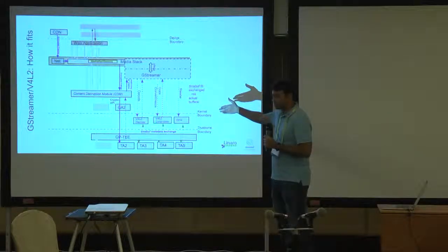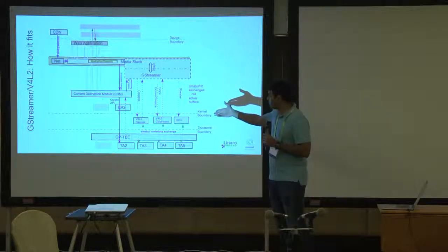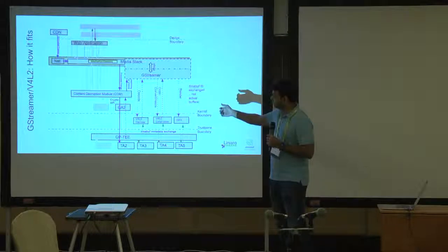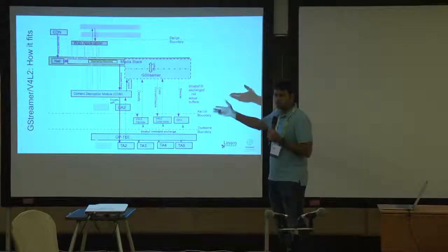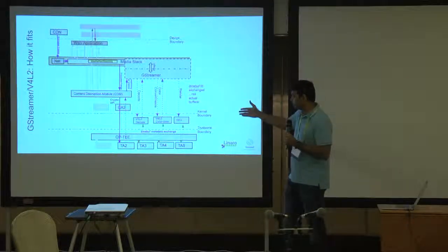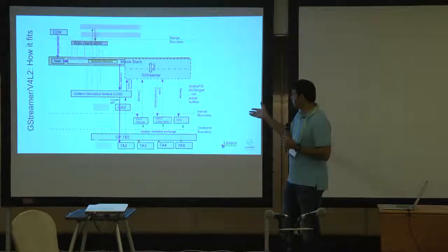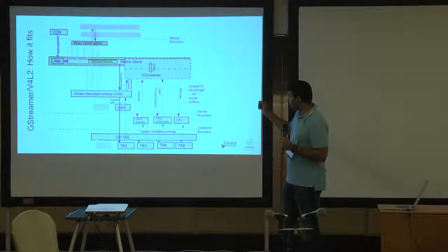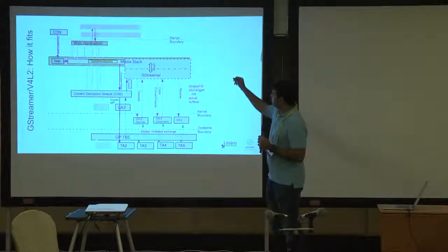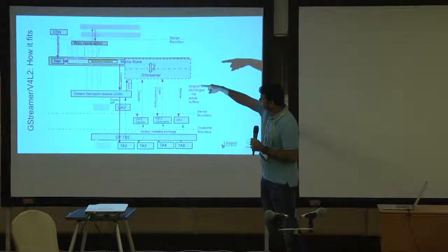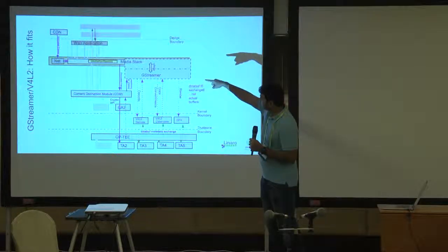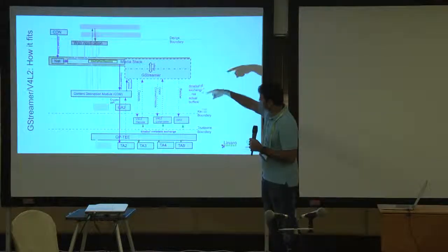You have V4L2 based color converters in the kernel. An example is the VPE engine from TI, or any other color conversion or scaler that can scale the images. And then you have a graphics engine. So GStreamer pretty much becomes part of the browser itself, and at that point, the DMA bufs are transferred back, and the decode happens.